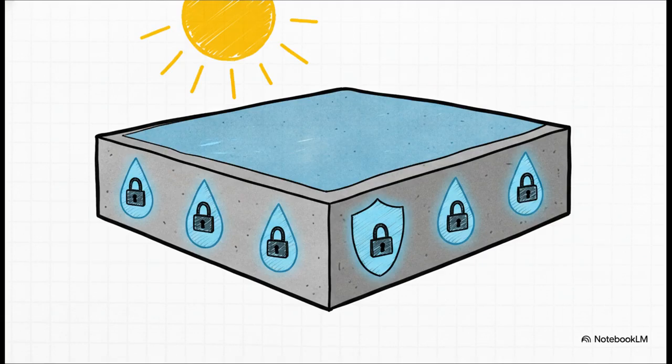So the crucial point here is a slightly counterintuitive secret: curing. You might think the goal is to dry the concrete out as quickly as possible, right? Actually, scratch that. It's the exact opposite. Curing is a race to trap moisture inside the slab. The ultimate secret to achieving maximum concrete strength is holding that water in to promote chemical hydration. If the water evaporates too quickly, the concrete will end up weak and brittle. So engineers trap this moisture for several days using water curing, wet coverings, or by spraying a specialized white membrane curing compound directly over the fresh surface.